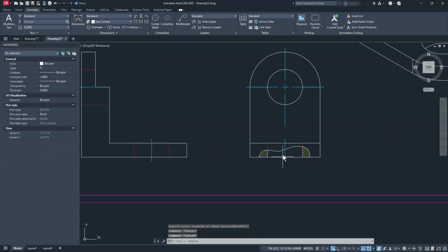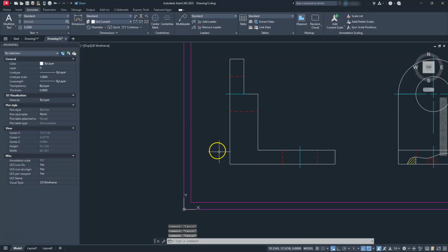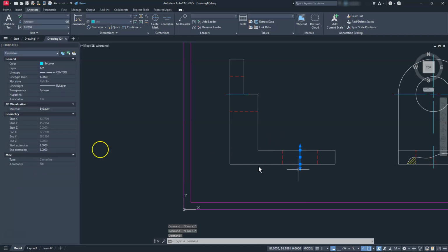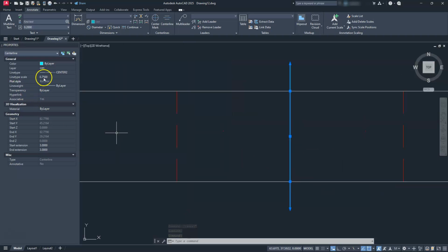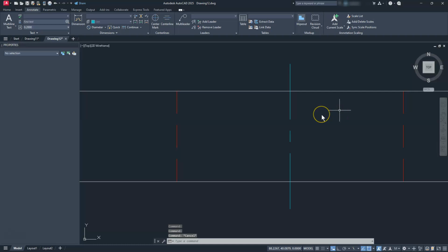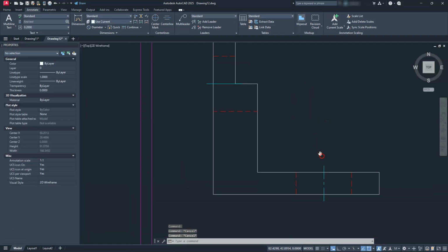All right. So now with my ones that are not showing any center lines or center marks, remember we need to make this one smaller. So I'm going to go here, and I always like to start off with 0.75 first. And if 0.75, let's zoom into this, doesn't show me anything, then I'll go to the next size, which is 0.5, and I'm breaking these down by quarters. Seems to work a lot easier for me if I do that, and those are nice easy numbers to keep in my head.